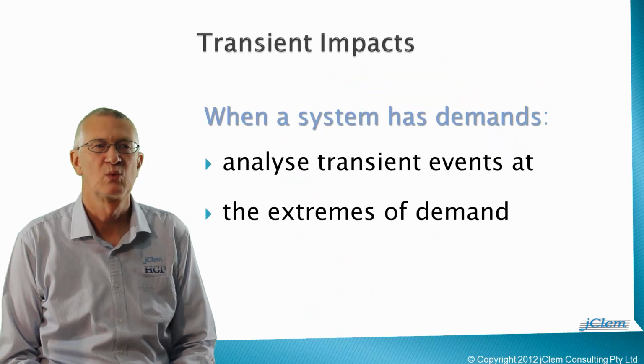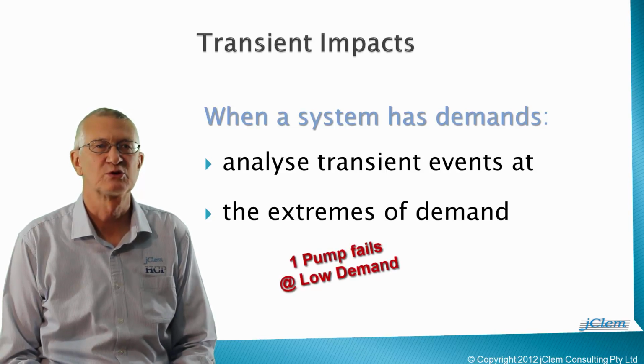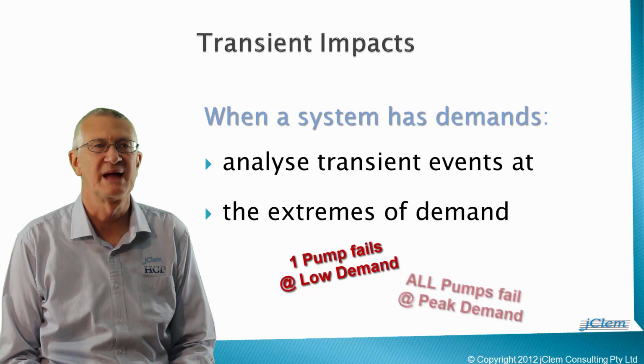Conclusion: when a system contains customer demands, designers need to analyse transient events at various extremes of demand. For example, the relevant scenarios could be power failure to the pump station with a single duty pump running and no demand, and power failure to the pump station with all duty pumps running and peak hour demand.